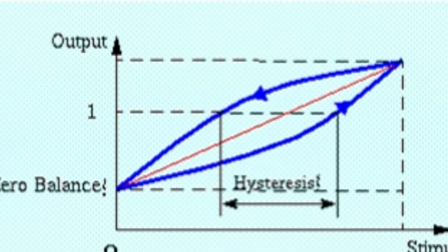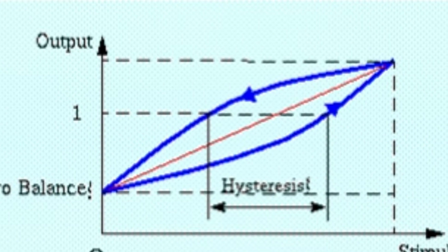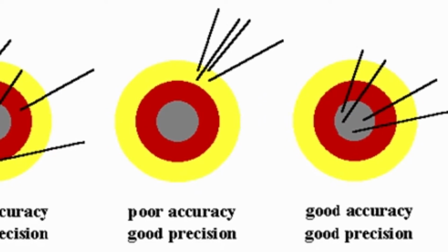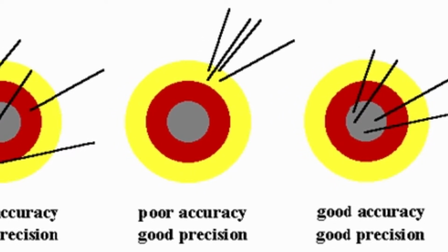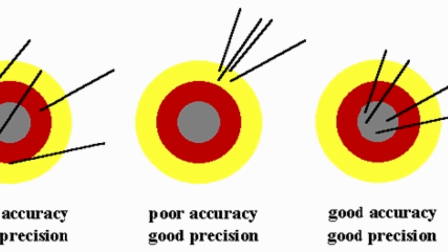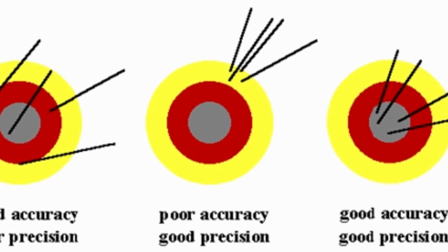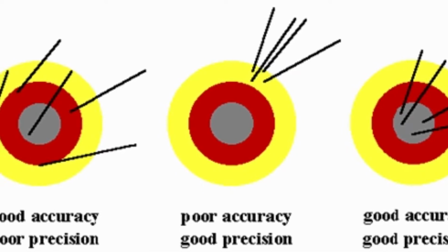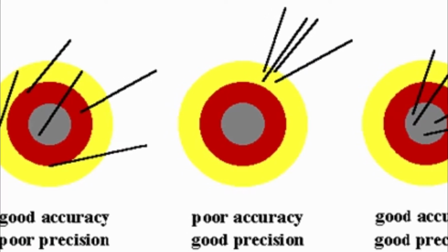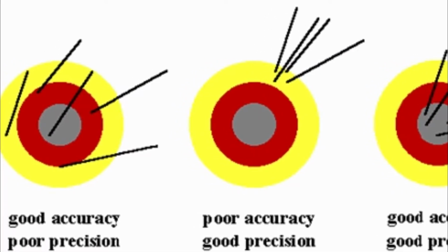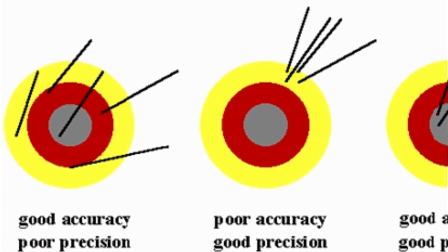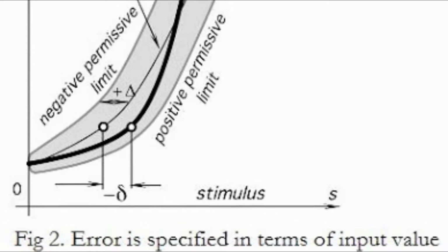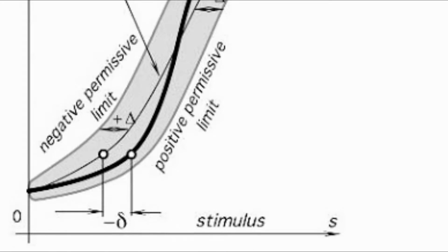Range. Every sensor has a range in which they work with an acceptable error. If the input is not in range, then the output is unpredictable. Drift. The signal level varies for the same input over a long period. This is called drift. The drift will cause an error in the measured value. The drift may result from aging of the sensor or temperature variance.